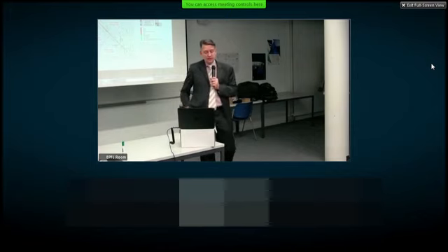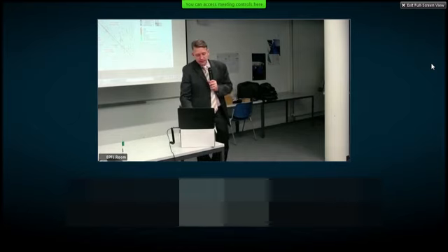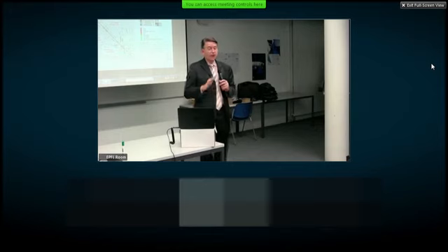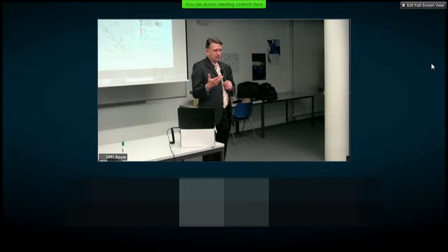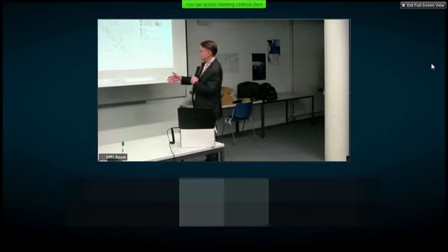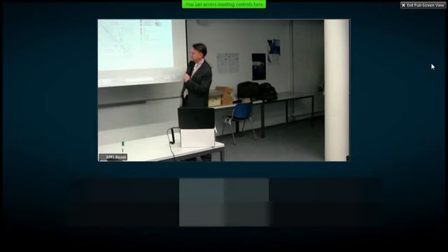So now these machines have to control the ozone, and essentially this box here, the printing engine, is sealed. It has its own air conditioning system to prevent the ozone from leaking out. It's a great example of how occupational safety drove new requirements, which then increased the complexity of the machine. So we keep track of the ozone flows. And then in green, we have the usual suspects: high voltage, low voltage, DC, mechanical energy, and then heat energy. So there's some coding that goes on here.